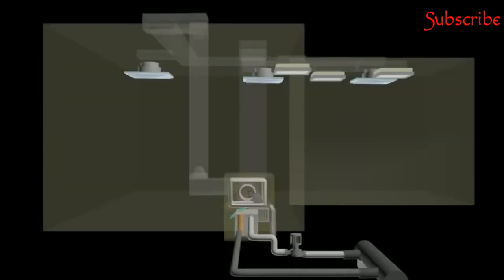The airflow system is operated using an auxiliary fan, which creates the air cycle from the room and mixes it with fresh air from the outside to the air handling unit and returns back to the room. The type of fan used is a centrifugal fan, powered by a motor and connected through a belt.